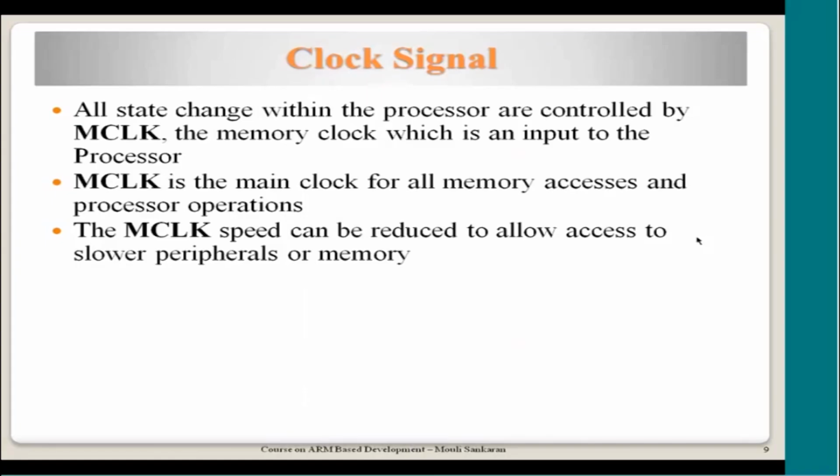You may wonder why this kind of flexibility is given in ARM. When the ARM IP is made, it could be integrated with any kind of system. It could be with a fast clock, or it could be integrated with memory and other systems which are very slow because power requirements are less, for a low end application.